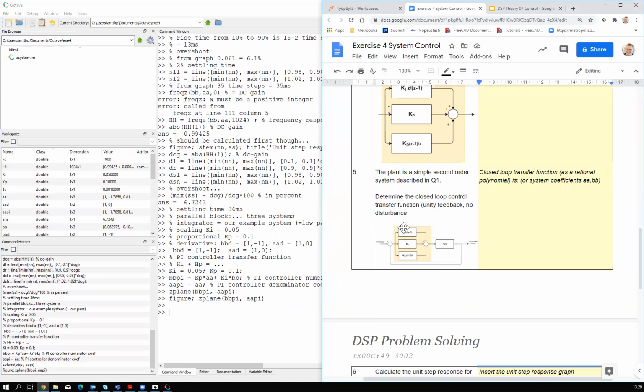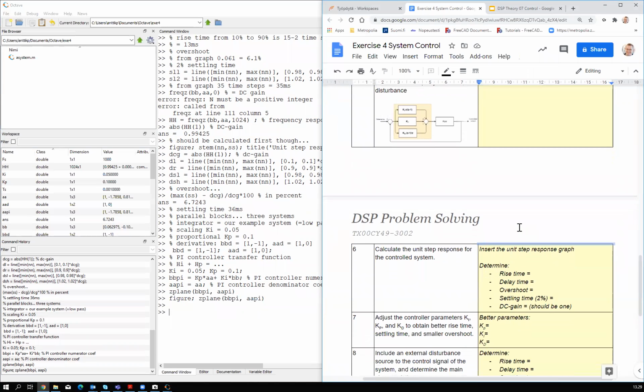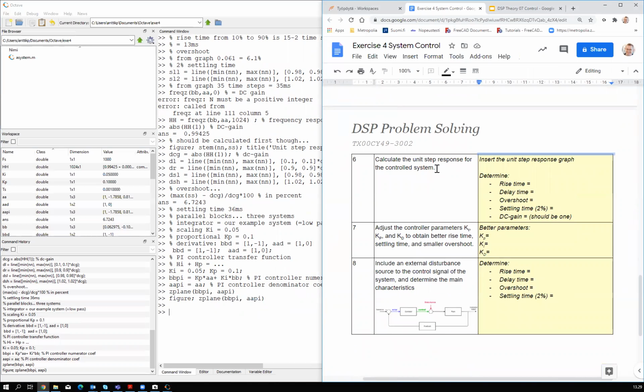All right, so then you just calculate the transfer function for that. What is a closed loop transfer function? That's straightforward to calculate. If you did it already on, say, the second exercise, that was quite close to that. If not, you now have a little bit more material for it. That's something you need to know how to do. You are an electrical engineer, damn it. Behave like one. You need to be able to calculate transfer functions, period.